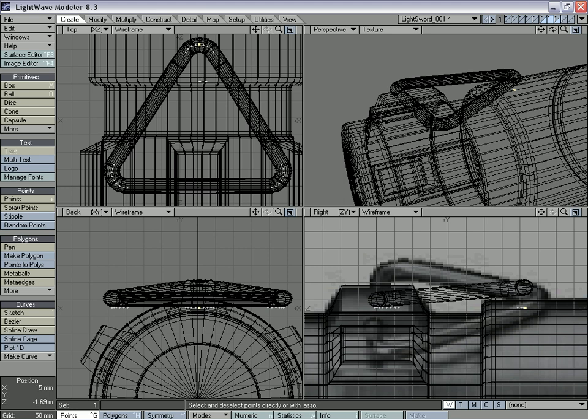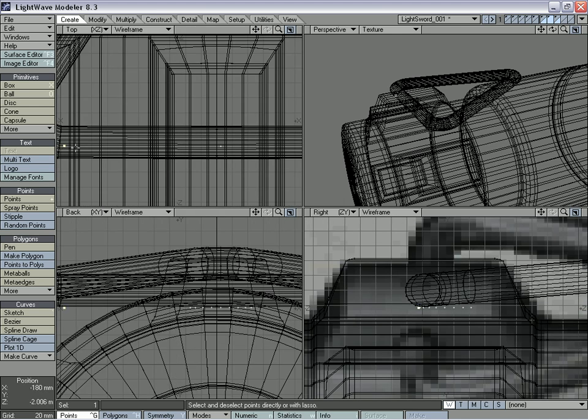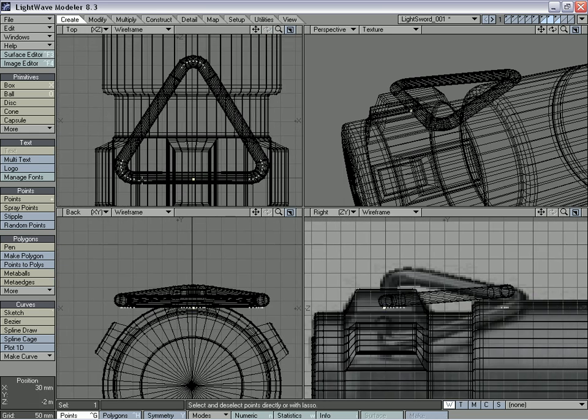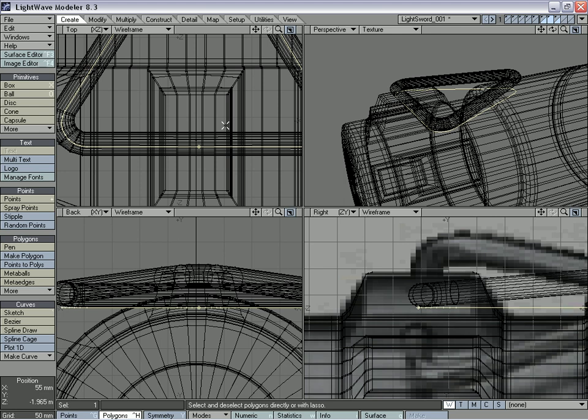and take this middle point, copy and paste, and just pull it in here into the center. And we want to copy and paste this and make sure it lines up. And it does. We delete that. And we're going to use that new point as our starting point for that spline. And I'll show you that in a sec. Select these in order, Control O to close it. And now you can see our starting point is this new point we've created right here.